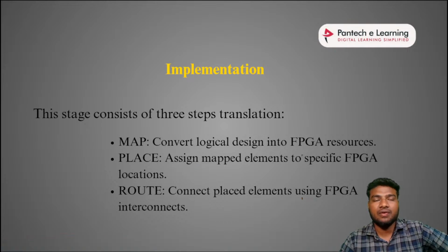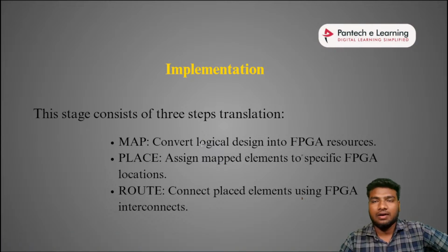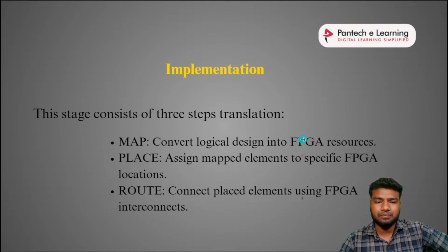We have to write only the code and simulate the design code. Mapping, placing, and routing are all taken care of by the tool. It will automatically assign the CLBs and the pins, and it will assign the output pins. We just assign the output and input pins. It takes care of the CLBs, latches, and lookup tables.